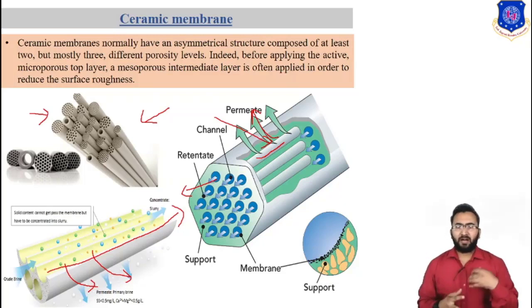Inorganic membranes are manufactured by a number of methods. These include particle dispersion and slip casting method, phase separation and leaching method, anodic oxidation, thin film deposition and so on. This membrane offers sufficiently high permeation and selectivity for the targeted mixture and can be made into a membrane module for practical application. However, large scale application of inorganic membrane requires further improvement in chemical stability and reduction in membrane cost.